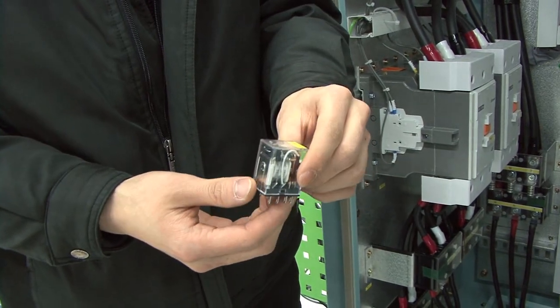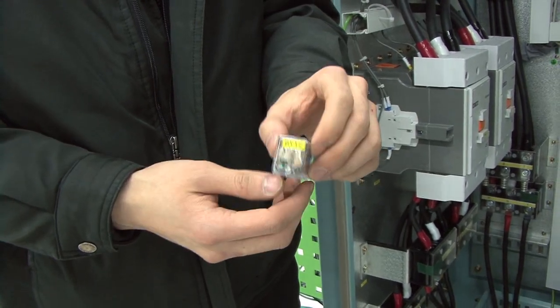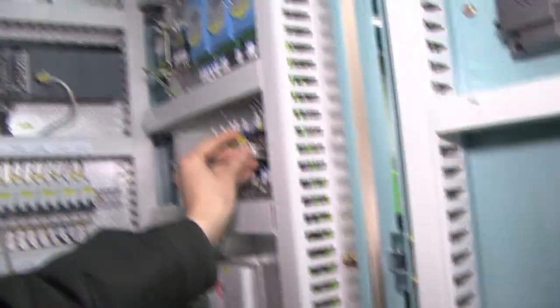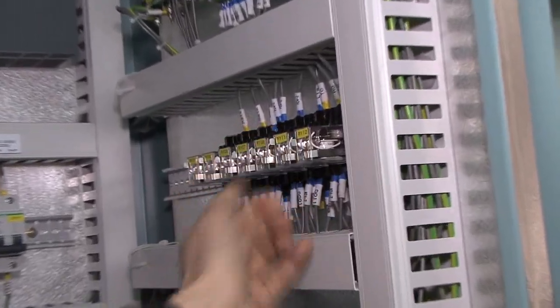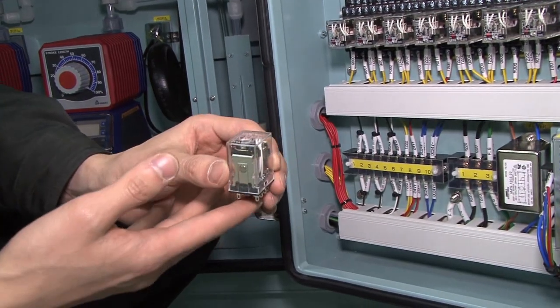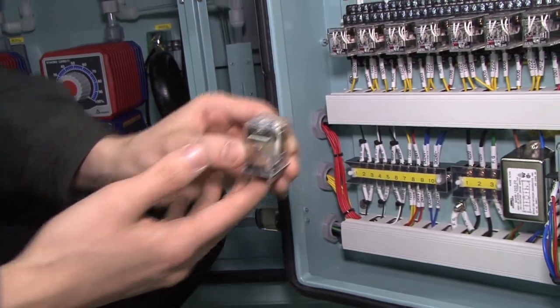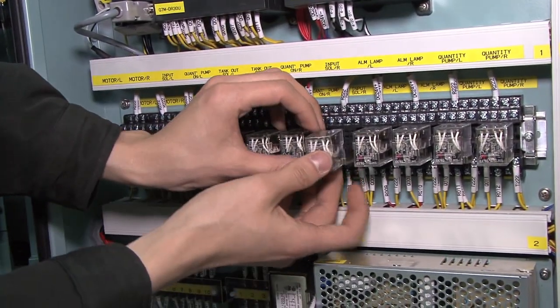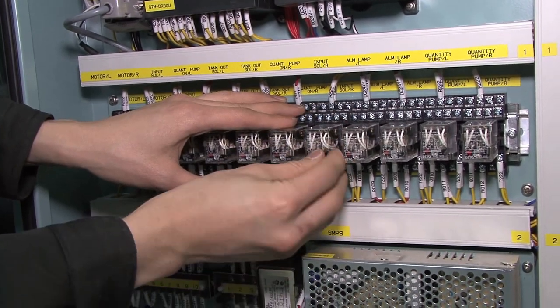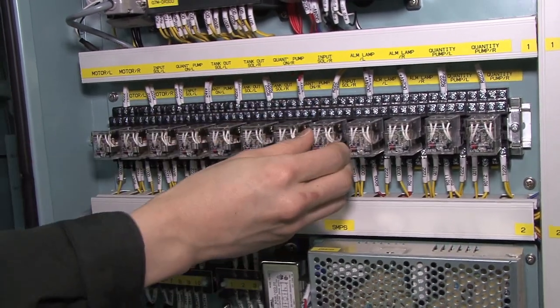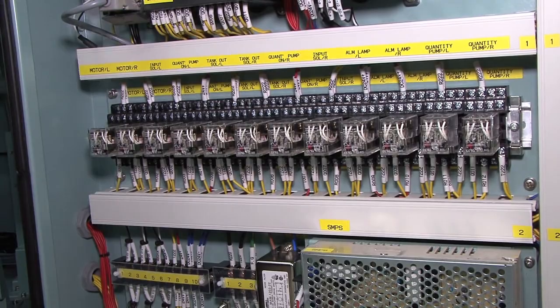Step 1. Remove the relay supporting hook. Step 2. Remove the defective relay by shaking up and down. Step 3. Install a new relay in the relay socket after checking voltages. LED lamp color: red AC 220V, blue DC 24V. Step 4. Check the operation, LED lamp light and operation state.